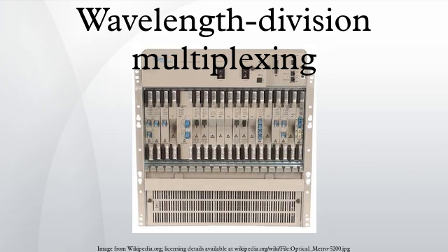Optical supervisory channel. This is a data channel which uses an additional wavelength, usually outside the EDFA amplification band. The OSC carries information about the multi-wavelength optical signal as well as remote conditions at the optical terminal or EDFA site. It is also normally used for remote software upgrades and user network management information. It is the multi-wavelength analog to SONET's DCC.